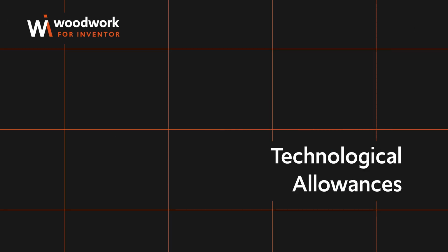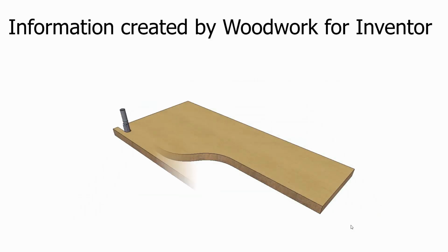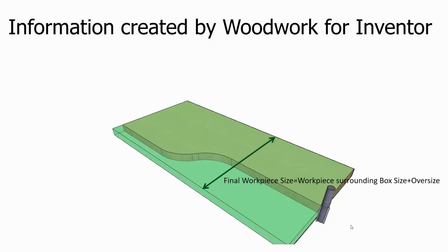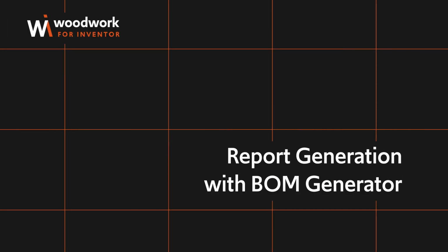Technological allowances. In addition, if there's any technological processing involved, simple dimension calculations are not enough. A technologist or another person responsible for finalizing the production data must be able to assign additional allowances for processing operations. These allowances are also reflected in the specifications, for example, when cutting is involved. This way, we leave a technological allowance for further operations. So, the blank size may change not only due to geometry, but also because the user has added these necessary allowances.